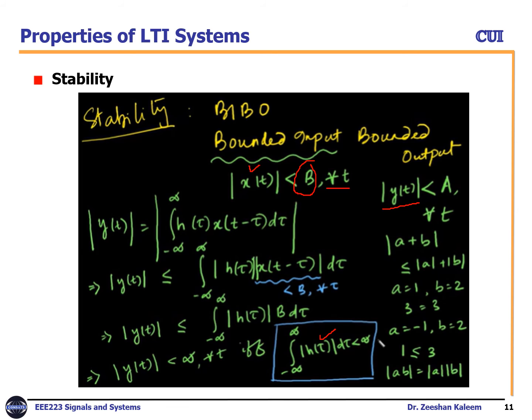Now let's convolve them. So you know that y of t equals the integral of h of tau x of t minus tau d tau. By using the commutative property, because usually x of t is here and h of t minus tau is there, but we can commute because of the commutative property for convolution, there will be no difference in the result, but this will help us to simplify the equation easily.